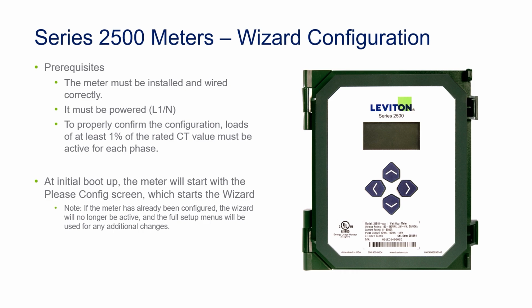At the initial boot up, the meter will default to the Please Configure menu, which is the first screen of the configuration wizard. If the meter has already been configured, the wizard will no longer be active, and the full setup menus will be used for any additional changes.